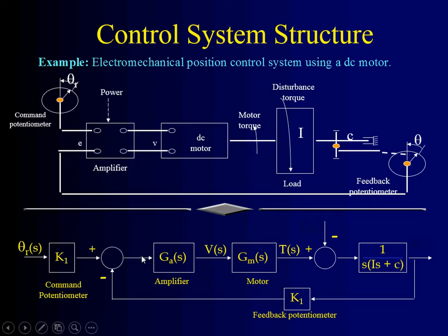So the control signal is a proportional constant multiplied by the difference between the set point and the current value. This is another way of saying error. Set point minus current value, read error. So if you multiply the error times the proportional constant k, you will come up with the control signal.